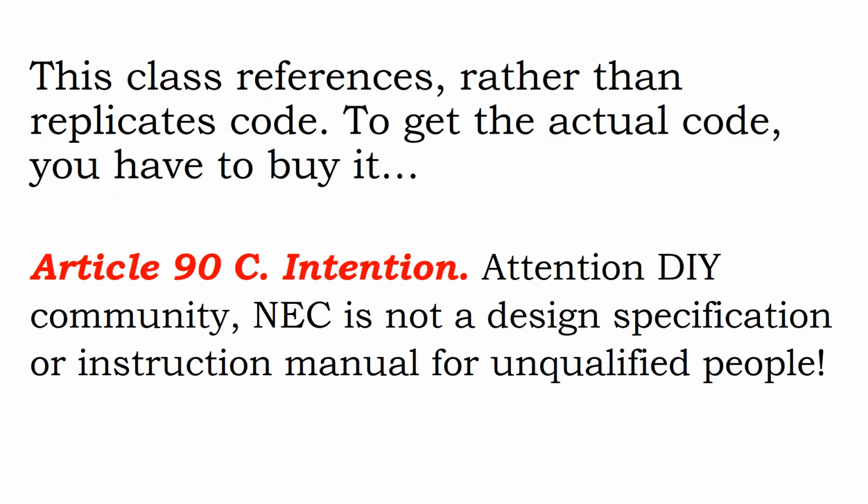If you're budget constrained, you go out and buy NEC 2011, and it's not like there isn't useful information in an older code book. In fact, the older your code book, the more simple the code is. So if you're just trying to learn code, buying a used, outdated copy of National Electric Code is not a bad idea. Although I do like the changes that they've made to NEC 2017. The battery sections of code are just being established, and so safety provisions are just being written into code for the first time. 2017 has clarified ambiguities in 2014, but there really isn't a lot of new stuff in terms of what a solar designer needs to be aware of.